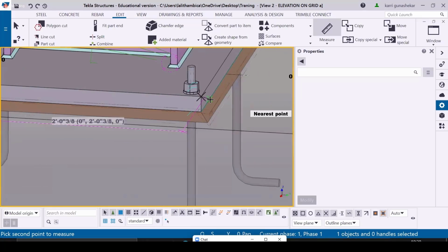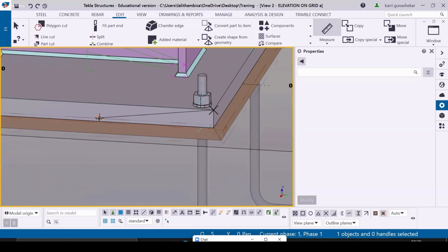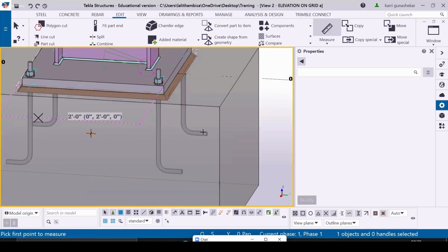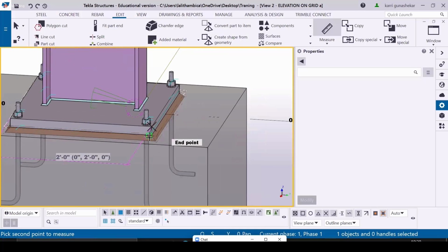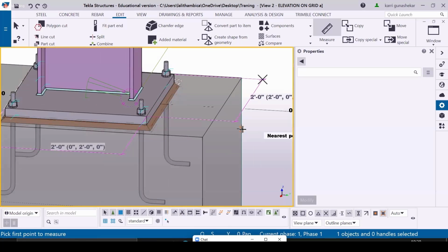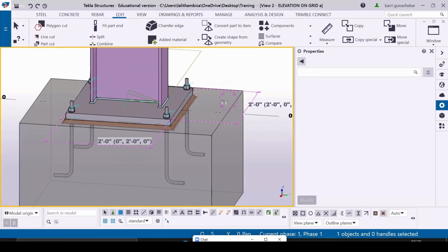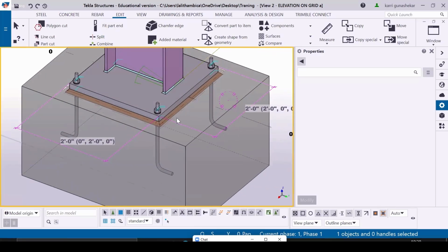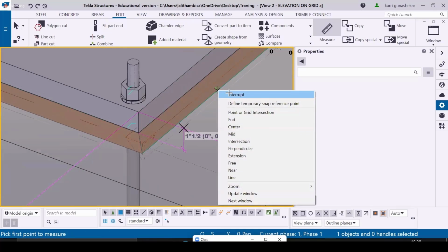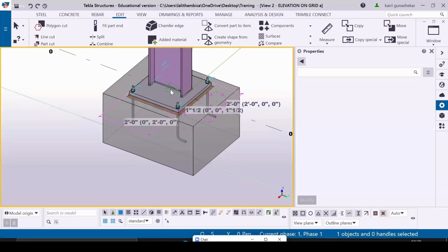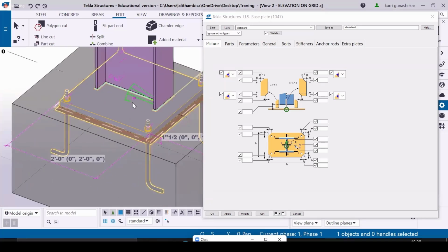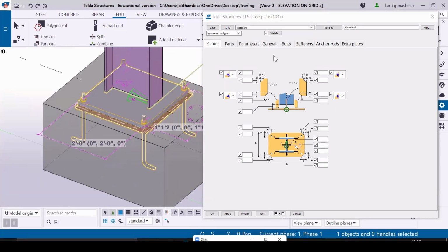Here the picking is wrong. See, this is 2 feet. This is nothing but height. This is 2 feet. And thickness, I have given 1.5 inch thickness. So these are the options we have modified in the part, in the component. If you double click that component, it will automatically open this window.